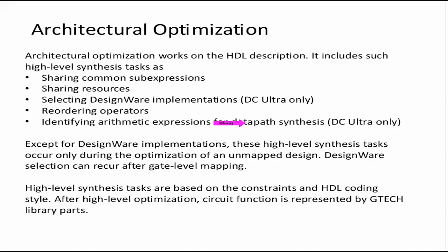What it means is that there are two commands for synthesis. One is compile, which is the basic compile command. The other is the compile_ultra command. The compile_ultra command is part of a license which is called DC Ultra. I'm not very sure whether it's available for you in the labs. Even if it is not available, it's not a big problem. Most of the trivial designs that we look at, most of the simple designs, the compile command is good enough.